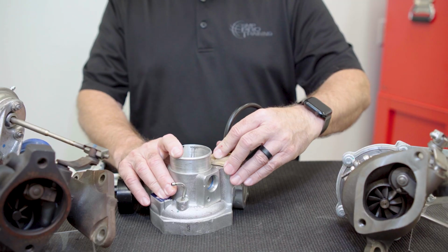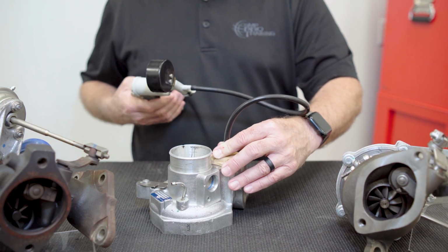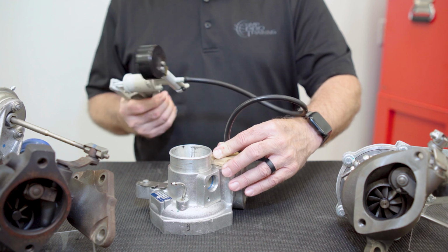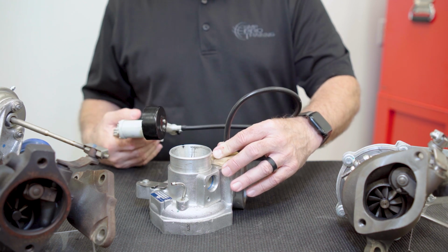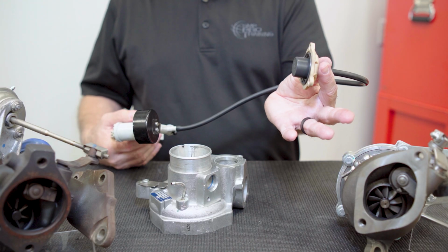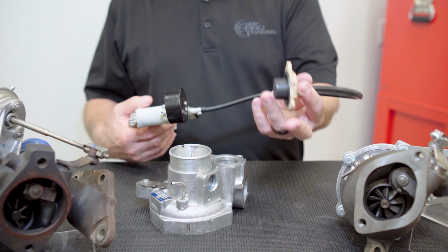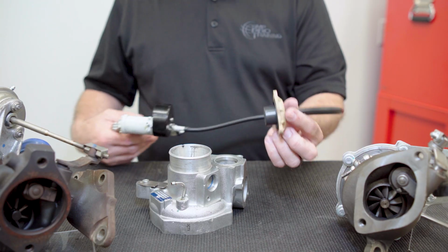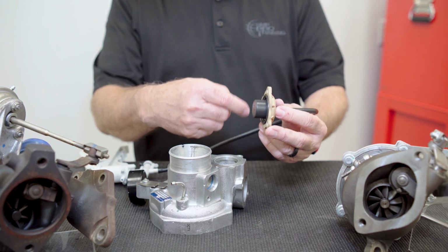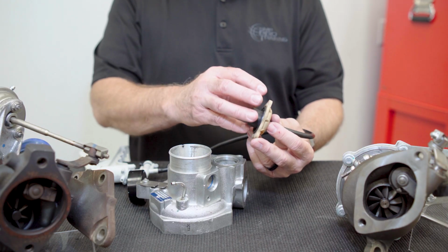And if we put it on, I've already got my vacuum pump set up for vacuum. I'm going to apply a vacuum, and if I've done everything correctly, the entire system should come out, and it does. If the diaphragm does not hold a vacuum for whatever reason, then chances are there's a leak somewhere. And if there is a leak somewhere, then you know, okay, well, this might be part of the problem.